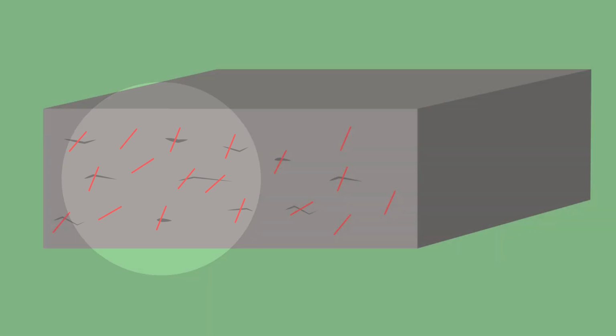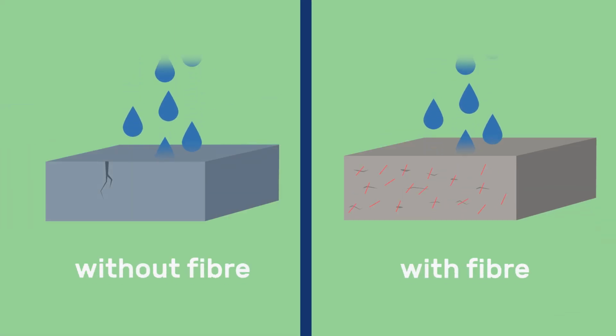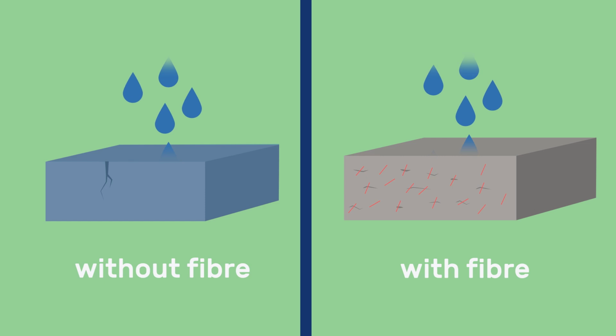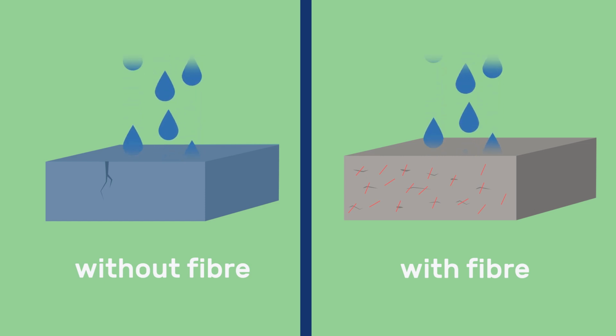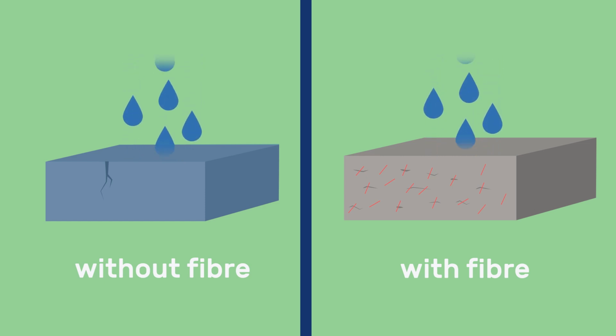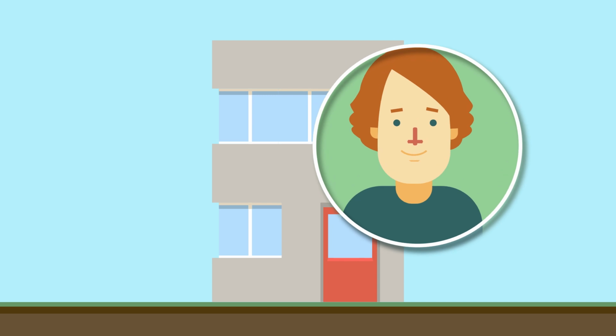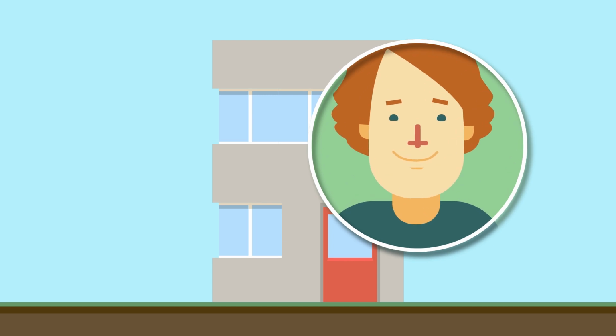These more numerous cracks do not have such a dramatic impact on mechanical integrity as fewer but broader cracks. This is also beneficial in terms of durability because smaller cracks reduce the rate of water sorption. Moreover, these microcracks may become invisible to the naked eye, which, for better or worse, reduces the risk of complaints.